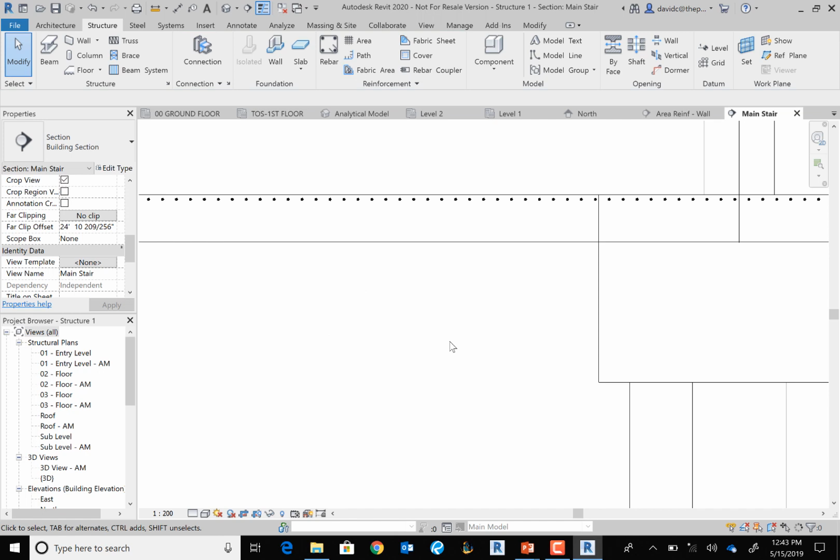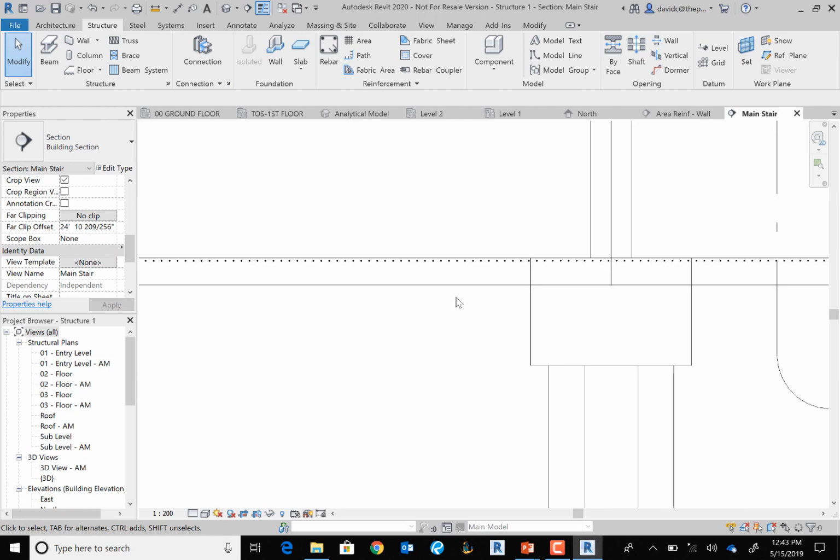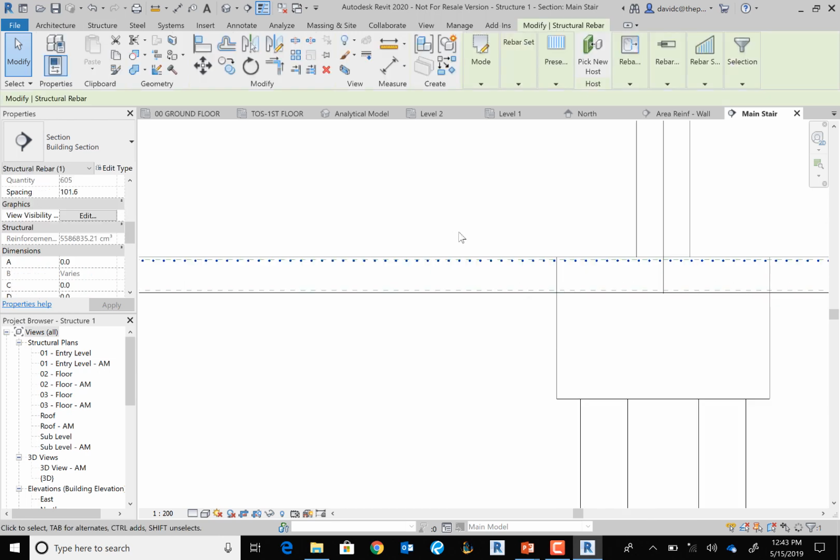I'll pretty much adjust the transparency of the wall itself, or whatever element is hosting the rebar, to bring it out. You still have to do something different for it to actually become a model element that exports in a 3D view for coordination. No, yeah, all of these are now model elements. The rebar is all, or should be. Oh, okay. Something like that, yeah. I mean, it's going to be there, but to export it, I would probably try to either do a filter by view, filter it down to just your rebar or those elements, or unobscure it.